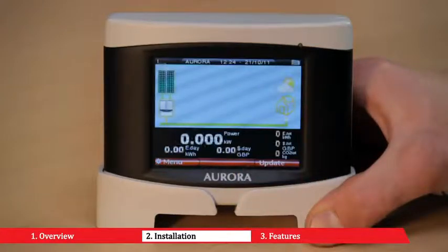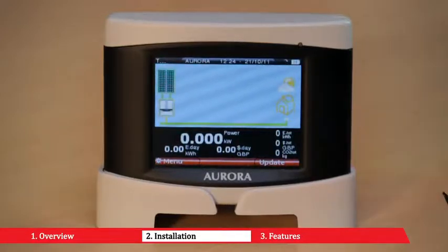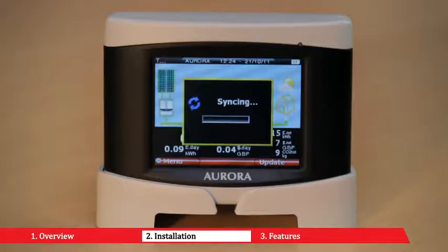Once the selection has been made, press the Next key on the display and confirm the choice. At this point, the system is configured and automatically starts the synchronization procedure. It is important not to interact with the device until this is complete. The first synchronization can take a long time because of the high amount of historical data that the inverters will send to the PVI desktop.